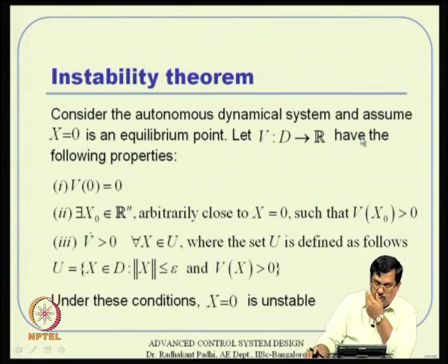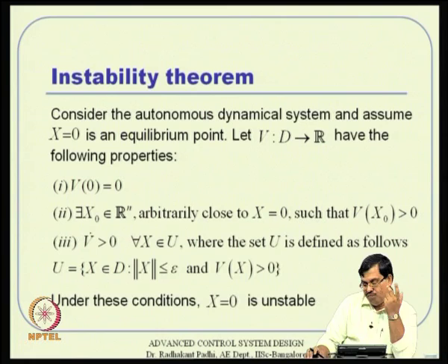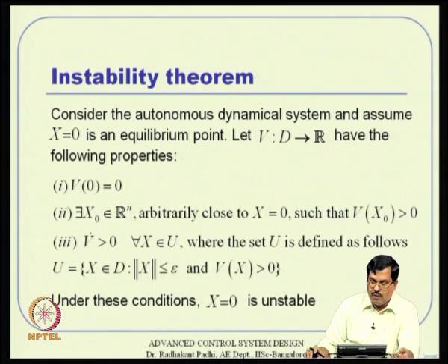Then on the way we discussed the instability theorem also, because all these Lyapunov theorems happen to be sufficiency conditions. So, if one selection fails, we are never sure whether some other selection will succeed or not. Because of those difficulties, people have thought about instability theorems, in the sense that if the system is really unstable, no matter whatever attempt you make at selecting a good Lyapunov function, you will never succeed.